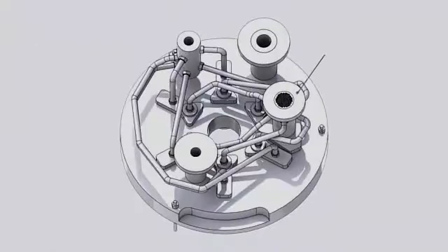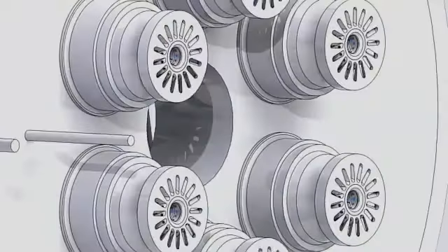Liquid fuel is supplied to a liquid fuel distribution valve to equally distribute the fuel across the 6 nozzles, especially on startup. Fuel flows through piping to the primary zone through the liquid fuel tip located at the center of the gas tip.